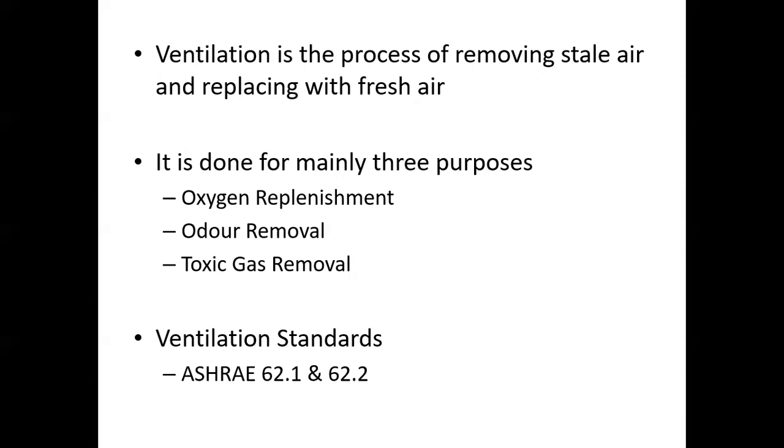Actually, it's up to the fan throw length itself and according to the capacity of the fan. Normally, a fan can throw up to 10 to 15 feet, okay, now from a high wall split AC. So that means you need to arrange those machines according to that aspect itself, if you are going with this kind of high wall aspect.